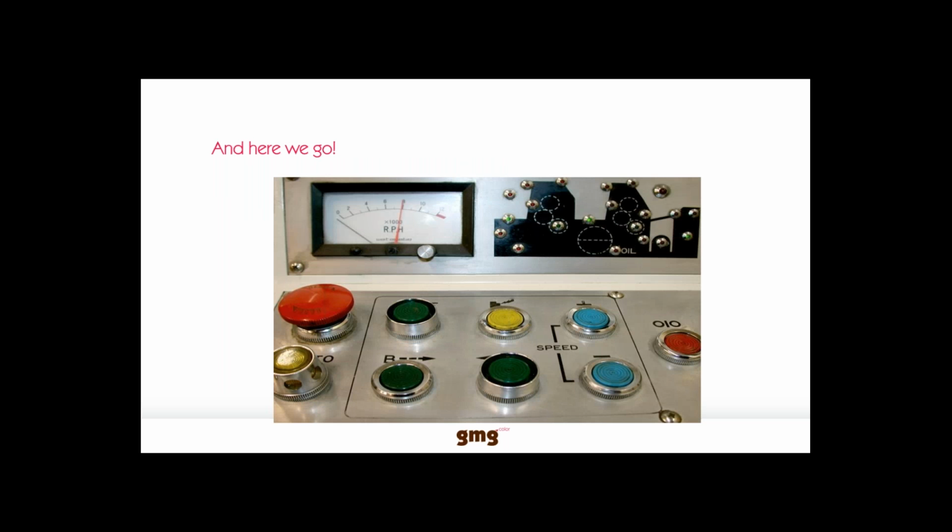And here we go. During the print run, you should pull sheets in regular intervals for quick evaluation, visually and by measurement. You should define an OK sheet that is closest to the predefined target values for primaries and TVI.